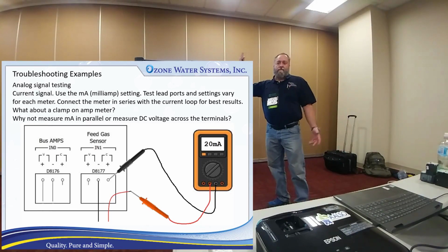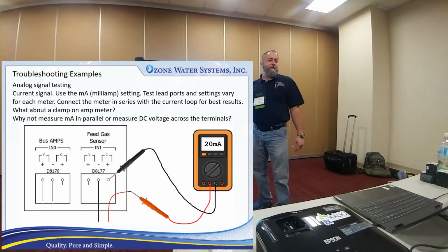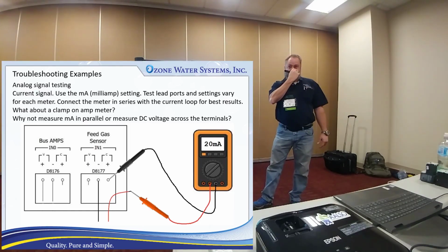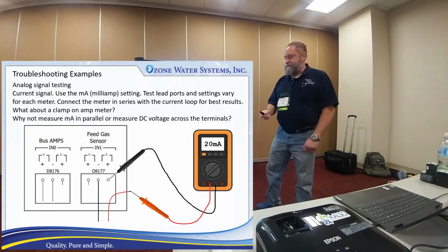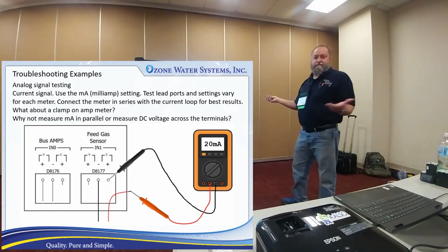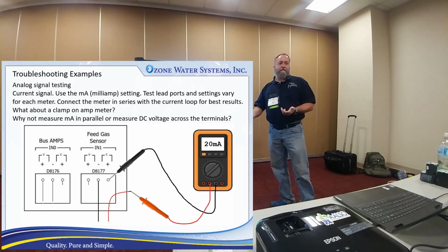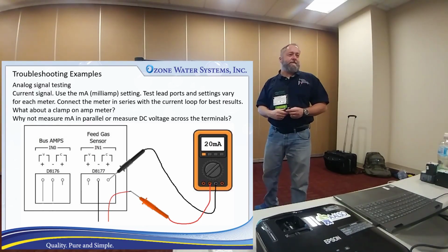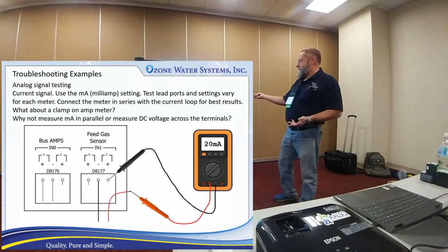So if your system is running, what's going to happen if it all of a sudden goes to minus 999 ORP? It's going to ramp up your generator if it's on a PID control. It's going to shoot up to the top. So, that could be a problem if it's a pump controller, maybe the same thing. Your pump just shoots all the way to the top and does something dramatic. So there's a place for it. If it's not running, yeah, you can do that.